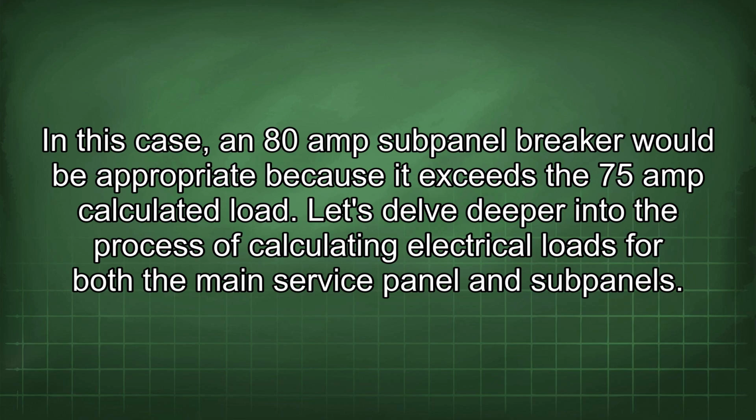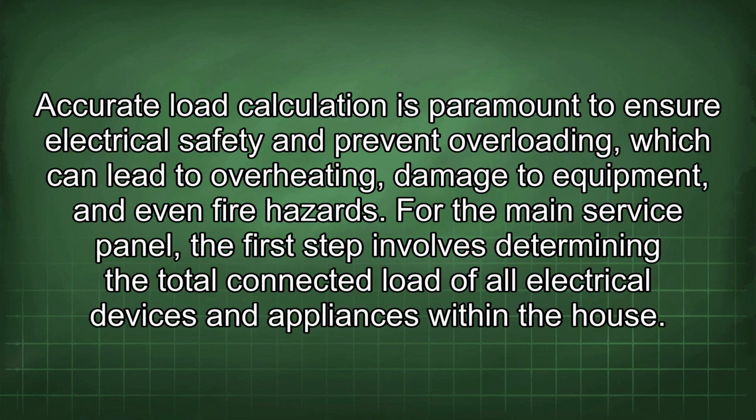Let's delve deeper into the process of calculating electrical loads for both the main service panel and subpanels. Accurate load calculation is paramount to ensure electrical safety and prevent overloading, which can lead to overheating, damage to equipment, and even fire hazards. For the main service panel, the first step involves determining the total connected load of all electrical devices and appliances within the house.